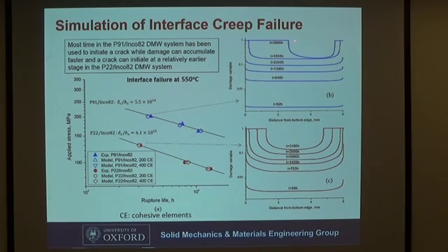Another thing, you may see, oh, this is not symmetric. Again, you can see from the Abaqus simulation, that is because the damage accumulation process during the simulation is very sensitive to numerical perturbation. That's why you see some asymmetric result here. But what's causing the difference between the two systems?